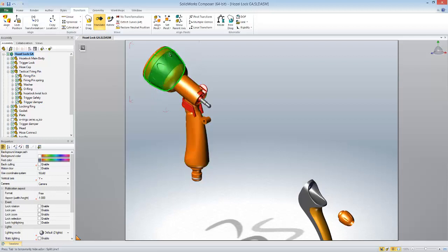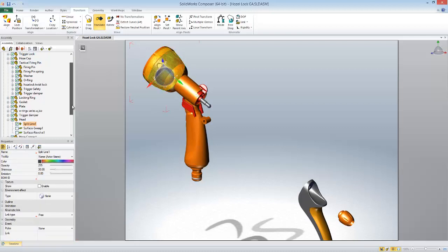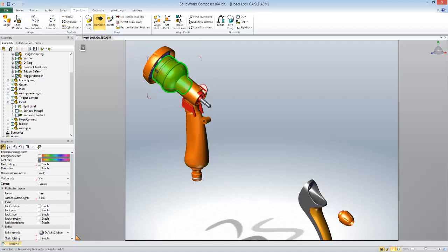So for instance, if I didn't want to have part of this head on in a specific view, I can literally just select it to see where it is in the tree here. So it's this one called head. Turn it off, and then you'll notice it's been turned off here. So views, another thing they can do is show you whether, or it remembers whether, a component is on or off. So it does more than just control where the camera's sitting at that point in time.